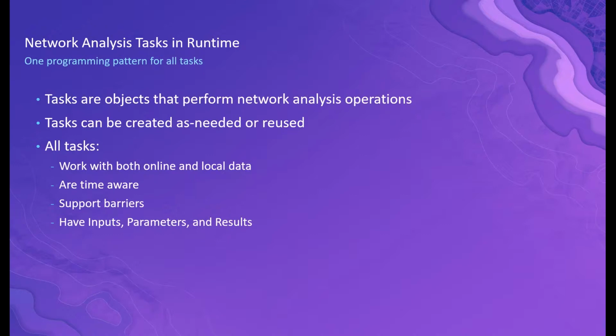So if you need to route or do any of these operations in the field without a connection to your server, you can deploy your data, your transportation network, and the solver through a mobile map package to your device. What's also interesting about this is, more than just taking normal commercial roads like you're used to using in your own phone, you can actually deploy your own custom types of geometry, whether it's things like your main supply routes, or trails and other private or non-commercial roads that you've been able to capture. You may even use GPS tracks and other information to augment the roads that you have collected before to get other routes that are available.